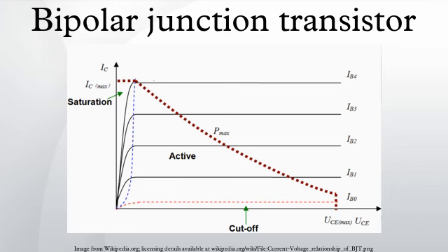H-parameter model. Another model commonly used to analyze BJT circuits is the H-parameter model, closely related to the hybrid pi model and the Y-parameter two-port, but using input current and output voltage as independent variables, rather than input and output voltages. This two-port network is particularly suited to BJTs as it lends itself easily to the analysis of circuit behavior, and may be used to develop further accurate models. As shown, the term X in the model represents a different BJT lead depending on the topology used.